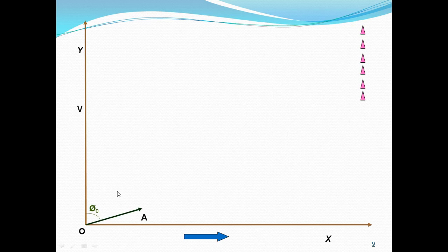See here, we have to draw like this. We take the voltage vector as the reference. So OA is equal to I naught at an angle of phi naught. Before drawing that, we have to select a proper current scale, convert the I naught value, and draw OA at an angle of phi naught.